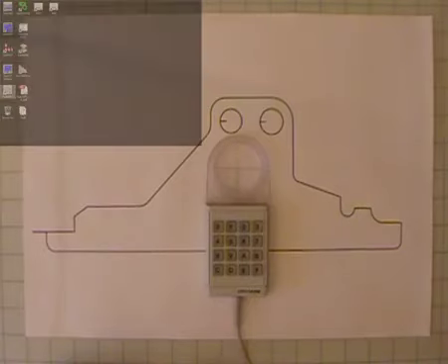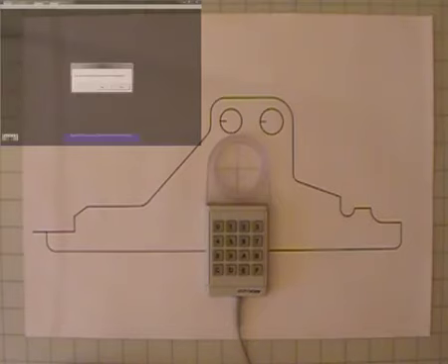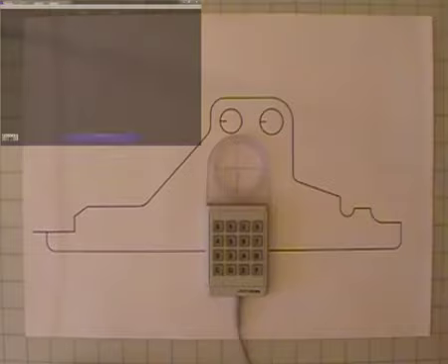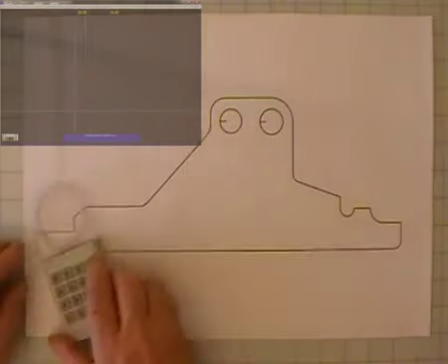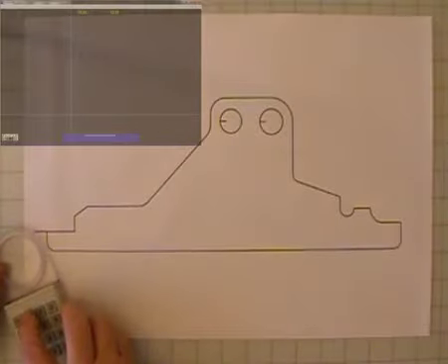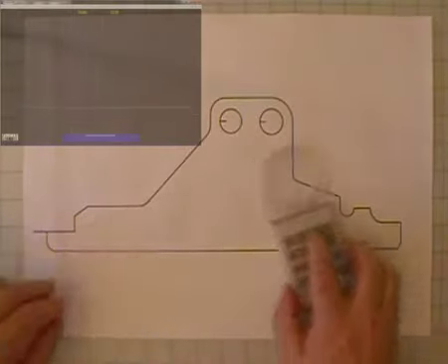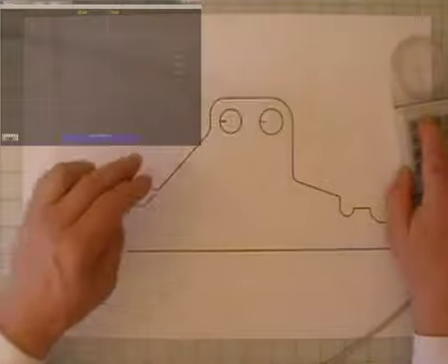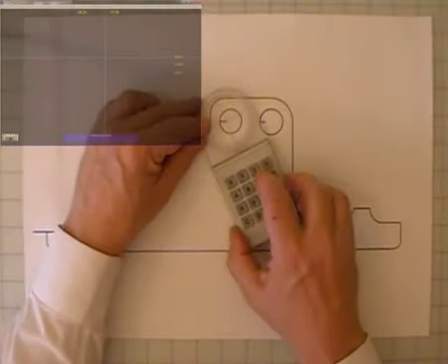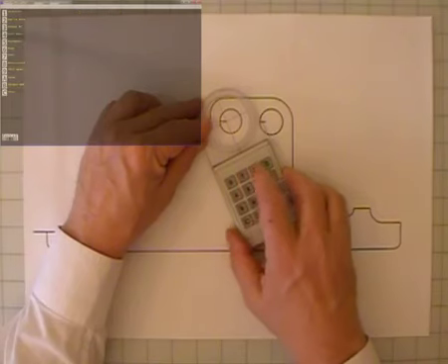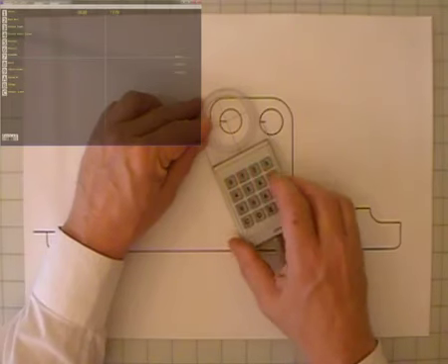There are some preliminary questions. You can recover an old digitization. You can scale the drawing, or set a new origin to digitize parts much larger than the digitizer. First, show the area on which you wish to work, bottom left to top right. You will now see how the screen follows the movement. The idea is that you can operate everything from the puck buttons without the keyboard.